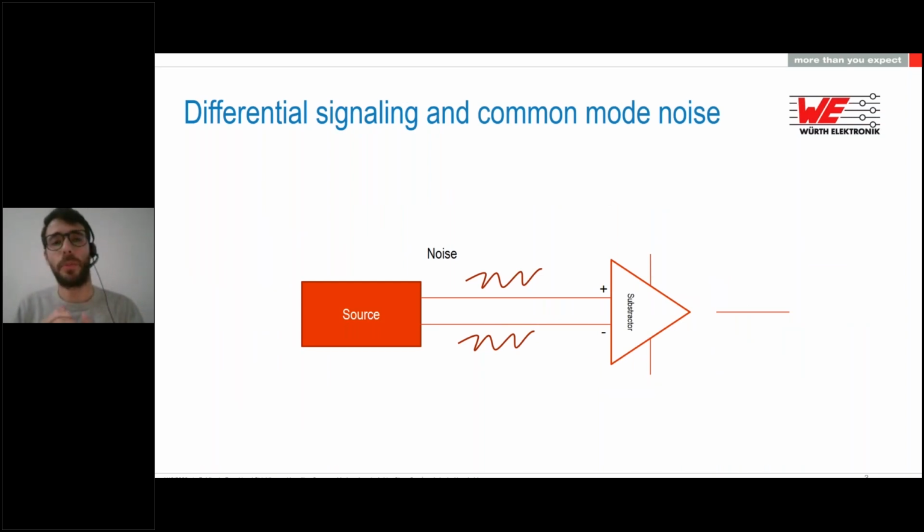The most common is the common mode noise. Common mode noise is where we have the same noise coupled on both lines in our design. This could come from a difference in the impedance between these two lines. We could also have different grounding references between positive and negative, and also parasitic capacitance. All these different and small problems can cause a difference of impedance between these two lines.